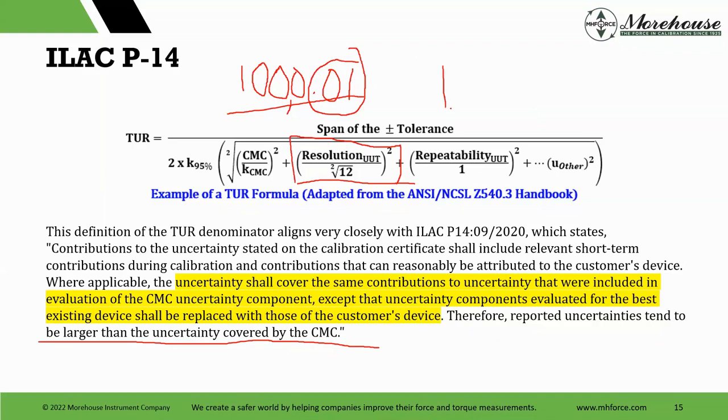However, if I was a manufacturer and I wanted a perfect instrument and resolution didn't matter, I would set my resolution to this, 1,000 counts. Chances of me seeing any variation at this digit in a dead weight machine, very, very low. So we can make perfect measurements the whole way up, 100, 200, 300. If we're not accounting for that resolution, we're not penalized at all.